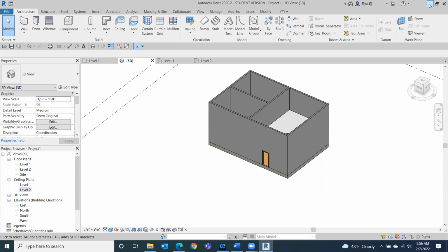So you're saving the same project every time you do this. As you save the project, it will save everything that you've created. If I do not save the project right now where I'm at, everything's going to go away, because all those things that we created are model specific. Some things in Revit are just set in the template, where it comes preloaded with walls and windows and comes with a certain amount. And then we can add new ones in when we add our component parts in, when we go to components and we add extra doors and things like that. But that has to be saved per model.